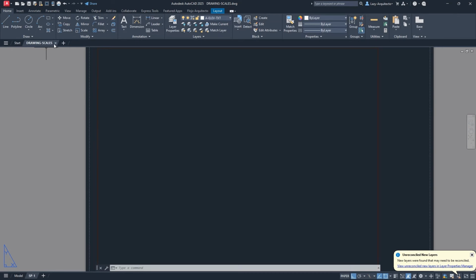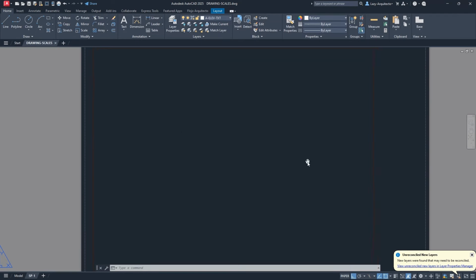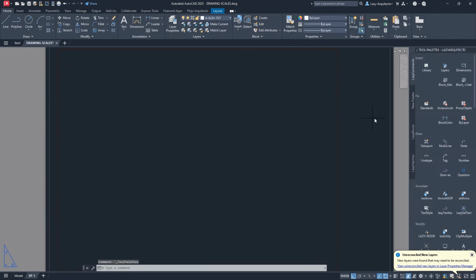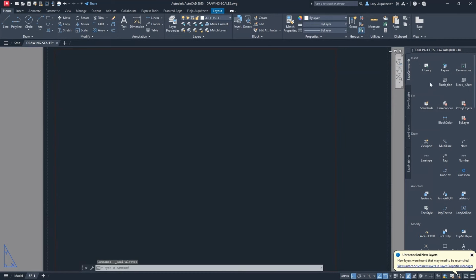All right. So in order to do that, I'm gonna open my tool palette with Control and 3. Now, you can see over here many custom commands that we have created here on the channel. These are also called macros. Anyway, so to create a macro, you can use the tool palette or you can use the command macros palette.